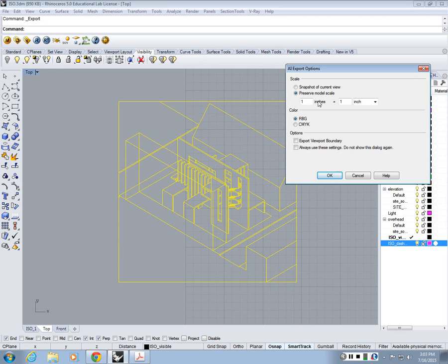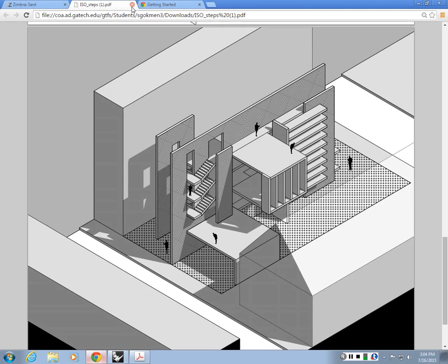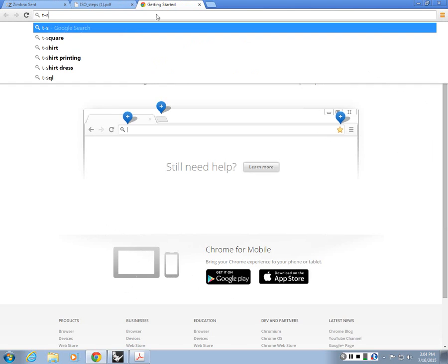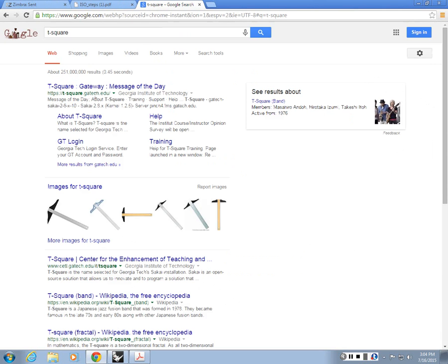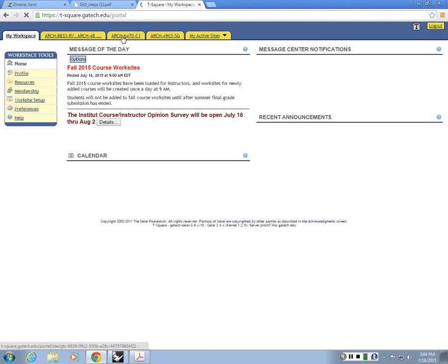Sorry. Because if you're modeling in feet, your artboard, the square you're drawing here, is 92, right? So that's 4 times the 23 inches. So your conversion will be 1/4 inch equals 1 foot. So 92 feet will become 23 inches when you open Illustrator. And I'm going to upload this file as well. So in case you don't have the tools I'm working with, I will let you use my Illustrator file.